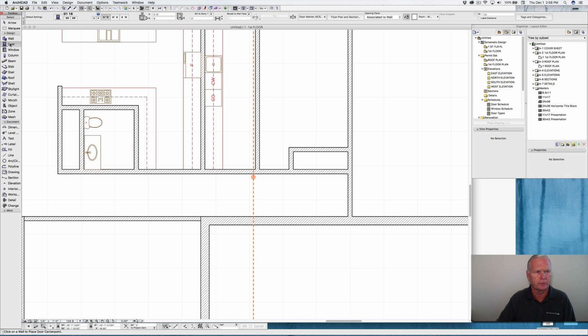And we're going to go back and click on the door tool, because we were in the walls a minute ago. So we're back in the door tool. It kept the settings that we had done for it. And now we're going to insert it. Well, we have insertion points here: center, left side, right side. And so we're going to set it for that anchor point. You'll come here, you'll see that there's the door and there's our anchor point.